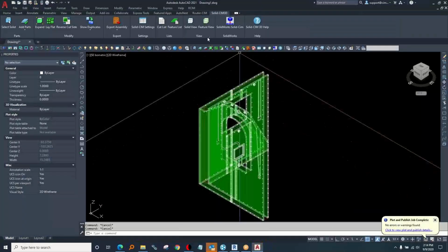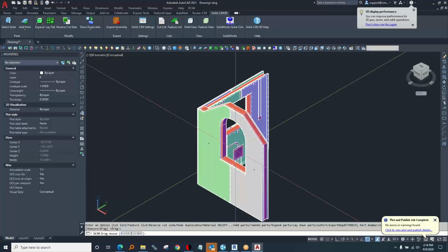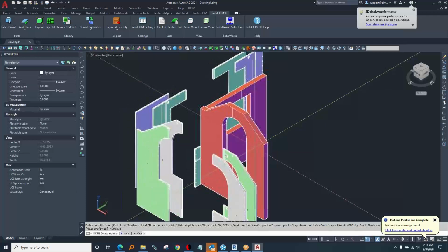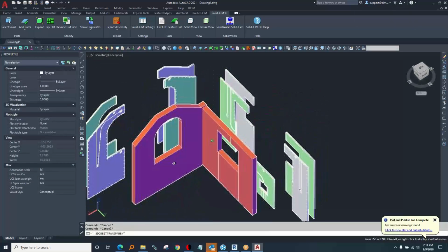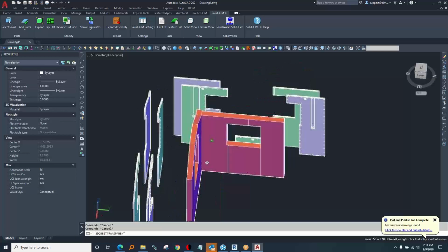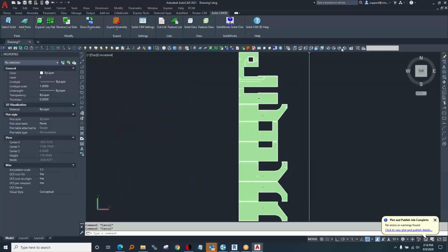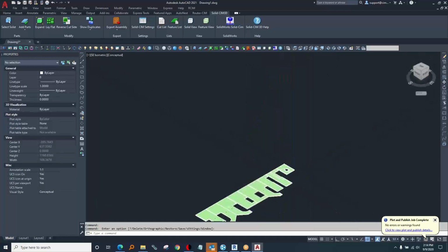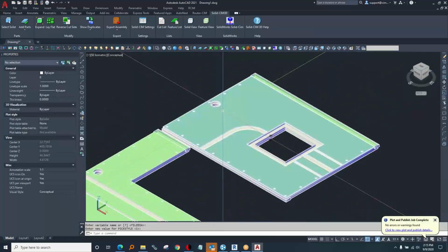Now it does leave you here in AutoCAD, so if you like, you can do an expanded view. Hold the mouse down and drag that out. And you could see that we had a setting there that ignored the 5-inch thick material that's red, but everything else is found. And then here's the lay flat. Lays those parts out flat for you. And that's where we got the feature recognition and geometry on different layers.